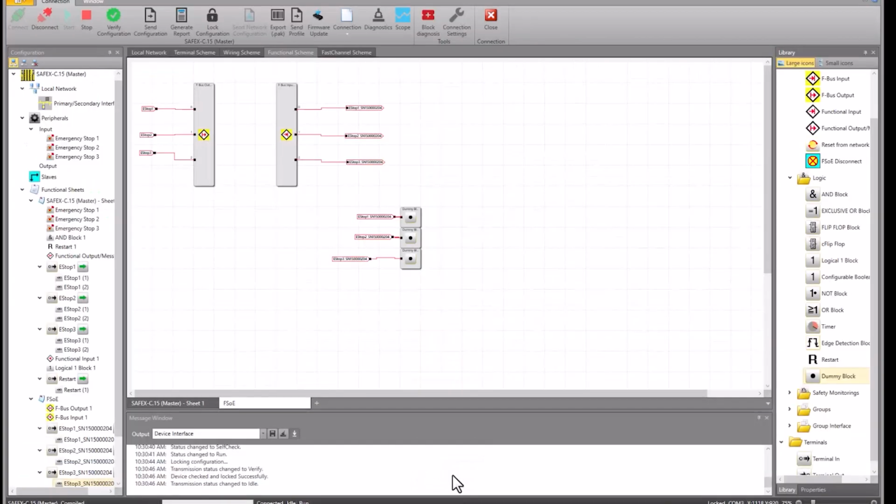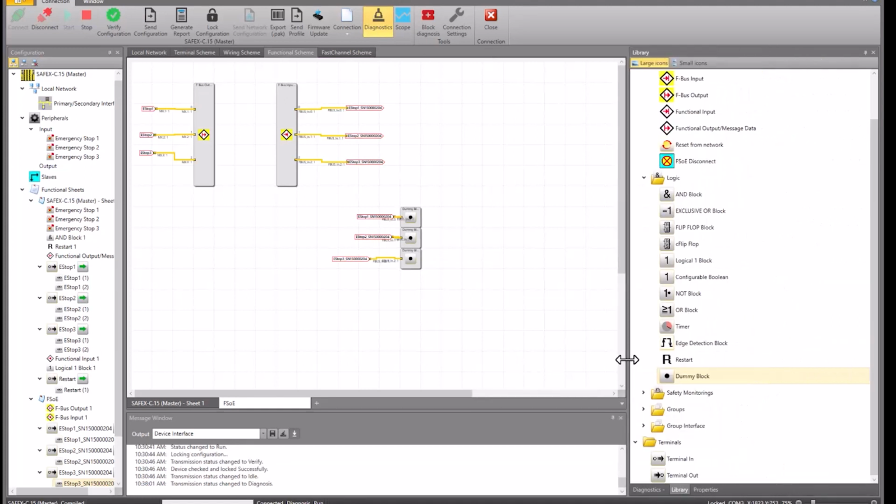Therefore we go now again on the Control X safety and activate here the diagnosis. I am now on the right control with the serial number 214 at the end, so if I now actuate inputs on the left control, I should see them here in the area.